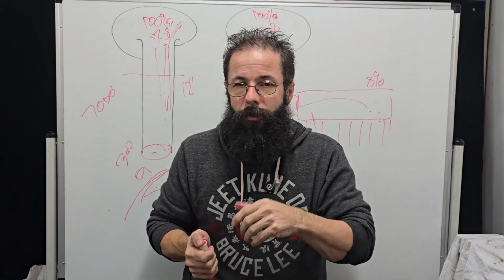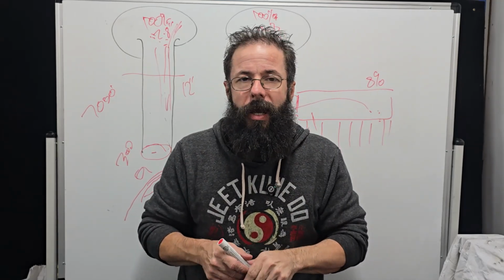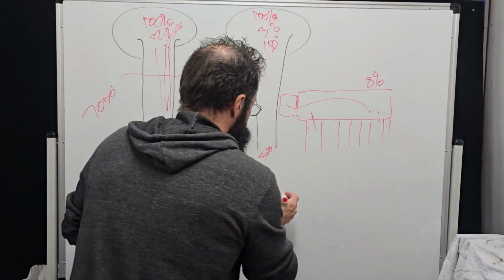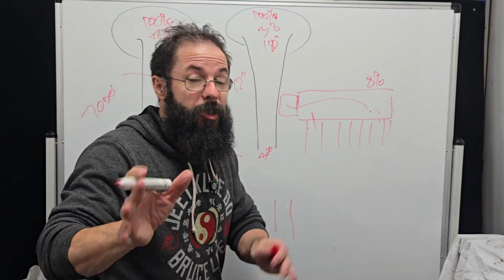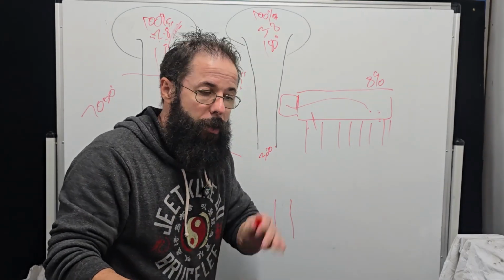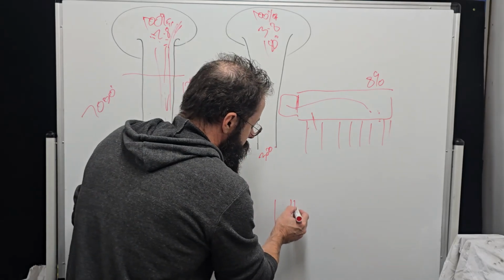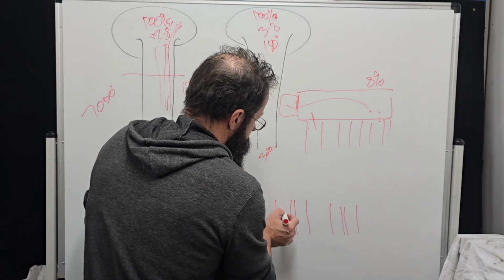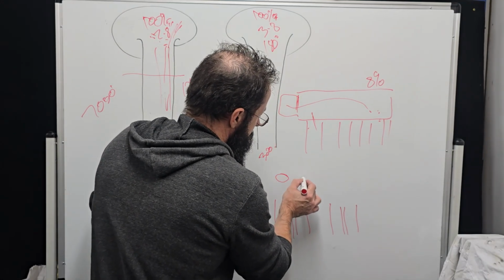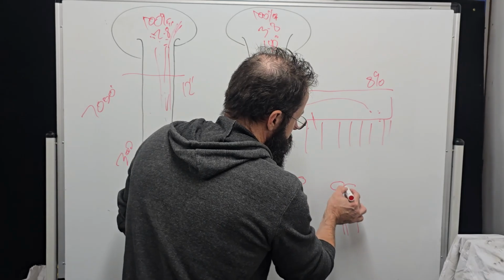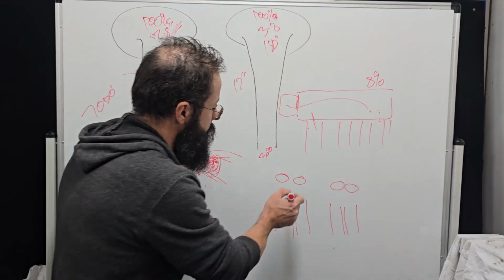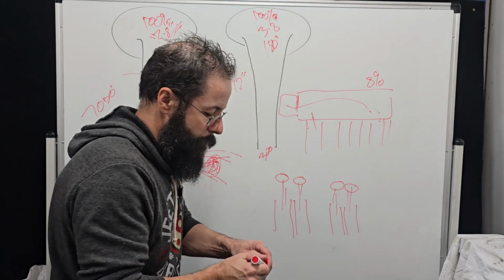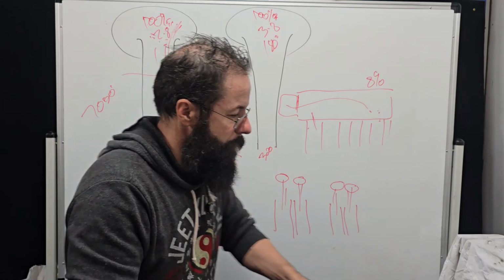This is why with some of the super stock and really, really quick drag races, we'll actually offset the carby plate. Which is hilarious, because they actually look horrible on the dyno. They won't do well, but at the track they'll do well. So we'll just use a small block Chevy for the moment, and say that's the runners, and here's our barrels. Ideally on the dyno, this is sort of where we want it, right? Because obviously the fuel's going to fall straight down, and we're going to get fairly good signal. Obviously there's going to be some jetting needed, but